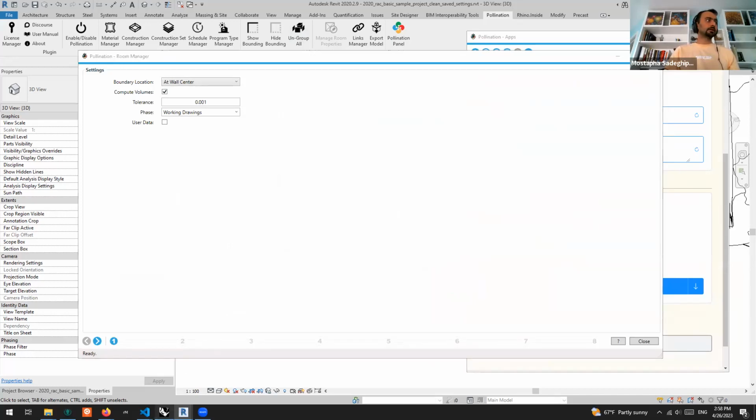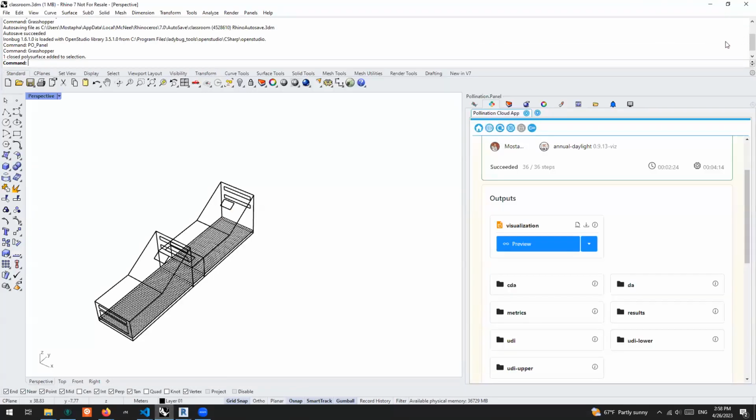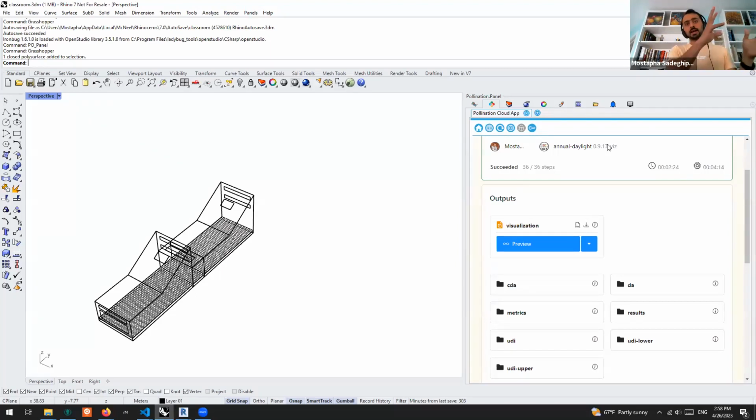Revit environments, right? So I wouldn't load my current Grasshopper recipe up into Pollination. No, it works differently. You can't deploy the Grasshopper script directly as a recipe, because Grasshopper is not as flexible to be translated to all the things that we're doing. Okay, but I guess you can still build in these modules. Yeah, because this recipe is also using the same Ladybug Tools that are inside those components in the Ladybug Tools Grasshopper definition.